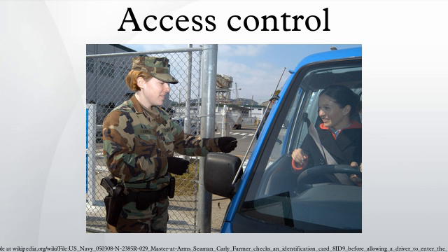Examples of such readers are RF-Tiny by RFLogix, ProxPoint by HID, and P300 by FarPoint Data. Semi-intelligent readers have all inputs and outputs necessary to control door hardware, but do not make any access decisions. When a user presents a card or enters a PIN, the reader sends information to the main controller, and waits for its response. If the connection to the main controller is interrupted, such readers stop working, or function in a degraded mode. Usually semi-intelligent readers are connected to a control panel via an RS-485 bus.